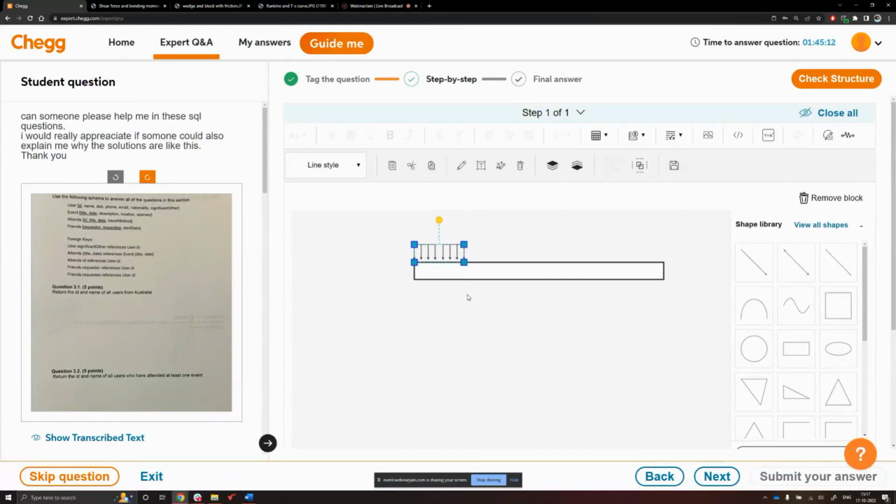Again, you can copy paste them, Control C and Control V. Again, copy paste. So if you just want to copy the single UDL, you have to ungroup them by clicking on this option, ungroup. Then you can again copy paste and move it here. Then you can decrease the size of the beam to accommodate the UDL, and you can add a line at the top so that the UDL doesn't appear to be broken.